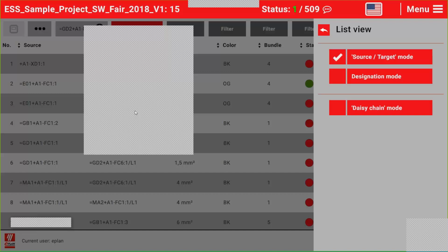Is it possible to put a filter on a wire bridge in a terminal? Through the Pro panel, of course, filters on wire bridges, technically the saddle jumper data that's been associated inside a schematic, that's basically where you manage that data. To put a filter on a wire bridge inside the terminal, this is something that you would have to do in the schematics per se.